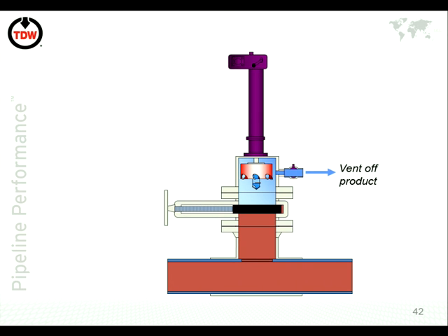You've sealed the pipe, the operation here. So you've sealed the fitting here with the valve. So this is still product, and that's product. This is being vented off, and then you would purge it. These days we tend to avoid venting off. It's captured somewhere, and then it's purged, and then it's inert at that point, so you can take it off.